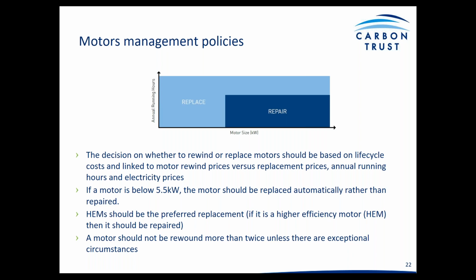If a motor is smaller than 5.5 kilowatts, usually it should be replaced rather than repaired, unless it's a very new motor that has been running for less than a year. But usually it's more convenient to replace the motor.